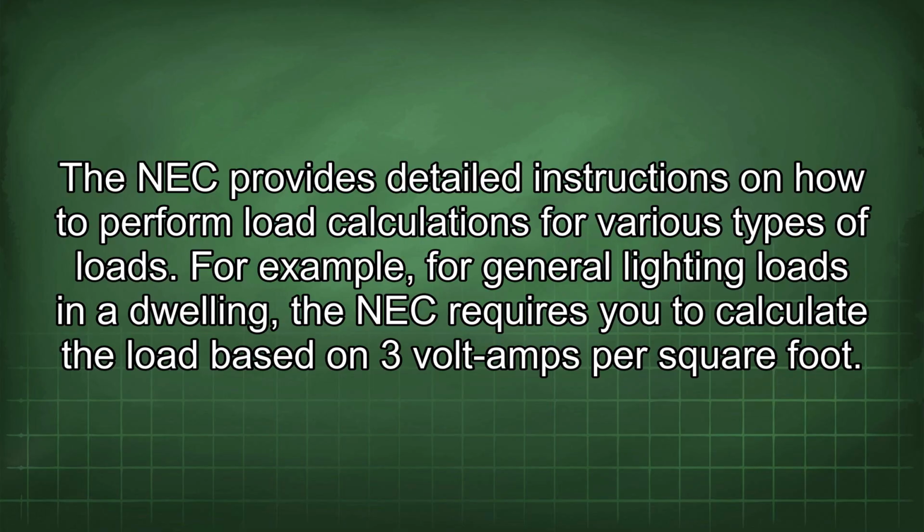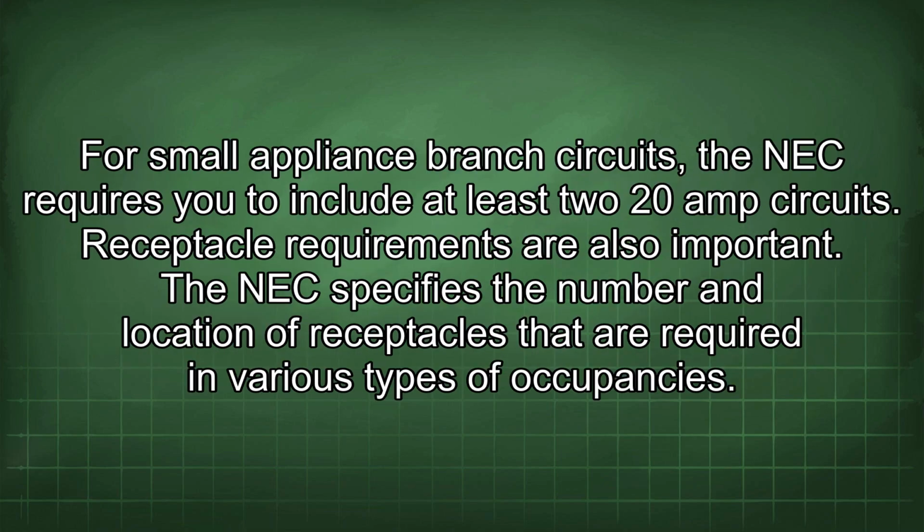For example, for general lighting loads in a dwelling, the NEC requires you to calculate the load based on 3 volt-amps per square foot. For small appliance branch circuits, the NEC requires you to include at least two 20 amp circuits.